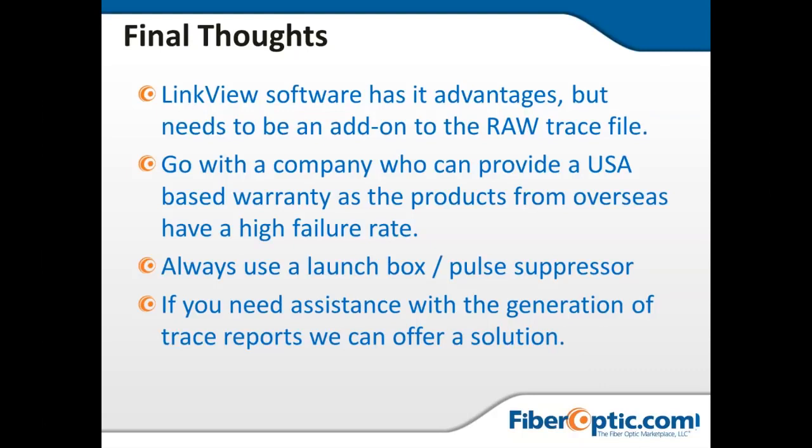And then if you need any assistance with generation of trace reports or things of that nature, that's another thing to consider: who's going to be doing that trace analysis. It's one of the things that we offer as a company. People send trace files to us, we clean them up, and do bidirectional analysis. But if you're going to request that a partner do that type of service for you, make sure that you're picking a platform that has a SOR type of file format that it can be exported to, because that's kind of the universal standard out there. Otherwise, you might have some sort of compatibility issues that may arise.